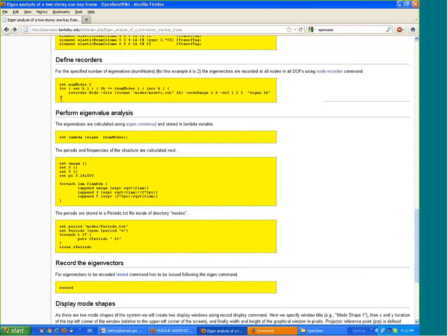I intentionally showed you this script as I find it very useful, not only for defining output files of your recorders, but also if you're running multiple ground motions on your model. Using this format command, you can create a nice model which will do all analyses at once in just one step.